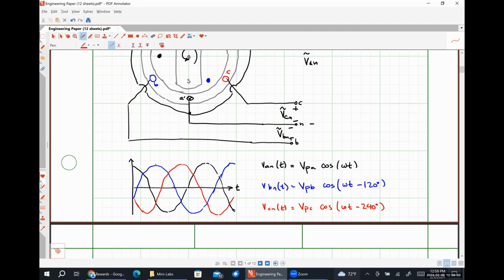So they will all have the exact same magnitude. So I'm now going to get rid of this A, B, and C. And from here on out, we're going to assume that all three phases have the exact same magnitude because the machine itself is manufactured in such a way to have a consistent number of windings in each coil, a consistent length of wire, et cetera, et cetera.